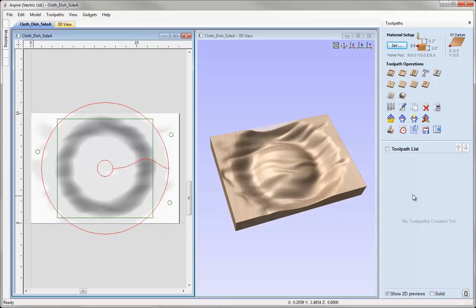Now the first thing we want to do is machine the dowel holes from this side. And I'm planning to try and use the same tool for all the toolpaths on this side of the job, and that's going to be a 1/4 inch ball nose tool. So I just need to make sure that I cut those dowel holes deep enough to account for that ball, depending on how long the dowels are and how much is going to go into the block and how much will go into our sacrifice sheet.